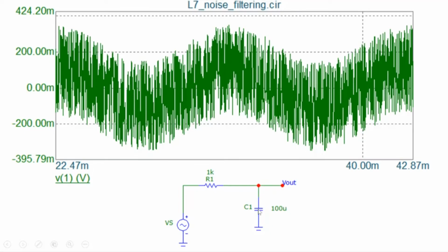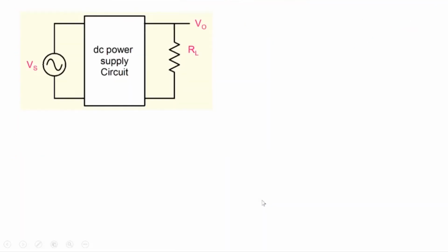And the charging and discharging of a capacitor, you would remember, would be controlled by how much current can flow from here, because the current has to supply charge, and the current is controlled by R. So if you don't have enough current, or if the R is high, then the capacitor can only follow the slower signals, and the faster signal the capacitor will not be able to follow. And that's how the signal gets cleaned. The high frequency noise components get rejected, and the signal of interest then remains here. So we're seeing a very important role that the capacitor is playing here in signal processing.